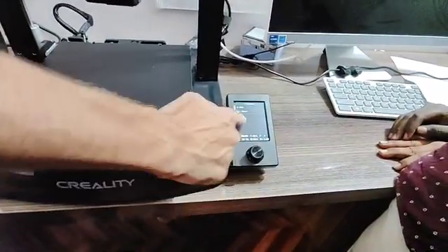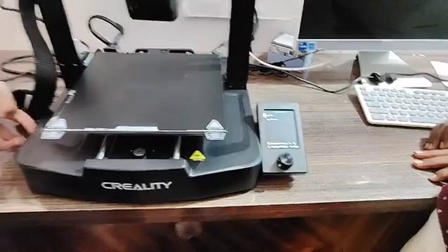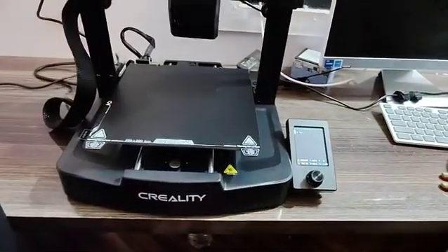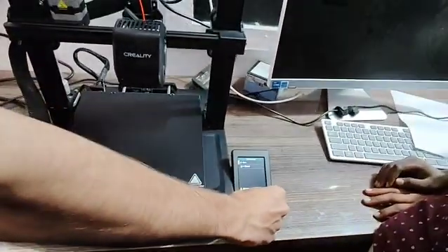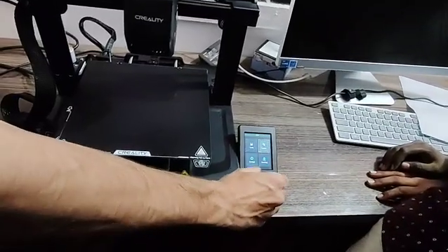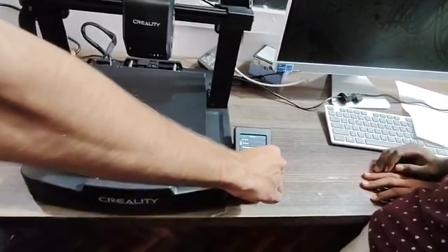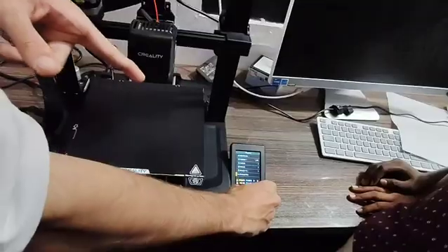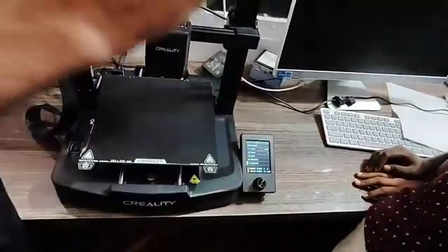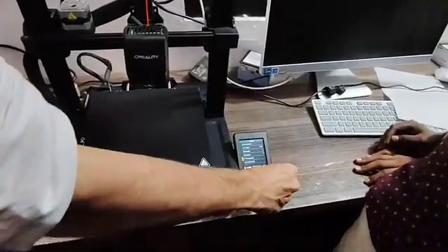Print option is where you get whatever the micro SD card has. The micro SD card goes here. If I remove this micro SD card, you put your design in the micro SD card and then you put it in your printer. It has a design, so it will show one design. Other than that, you have prepare. Prepare will allow you to move the axis manually. Then you have extruder, extract, and preheat. When you want to insert the filament in the 3D printer, you preheat PLA.